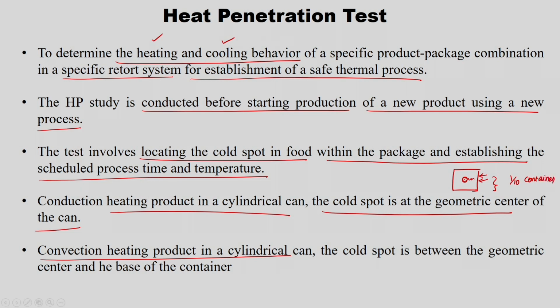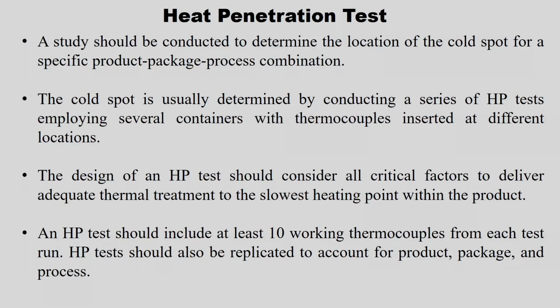And also, for example, if I have a solid particle in the liquid, then it may be between the bottom and the height to the geometric center of the container. So, somewhere in between it lies. So, in a heat penetration test, a study should be conducted to determine the location of the cold spot for a specific product package process combination.